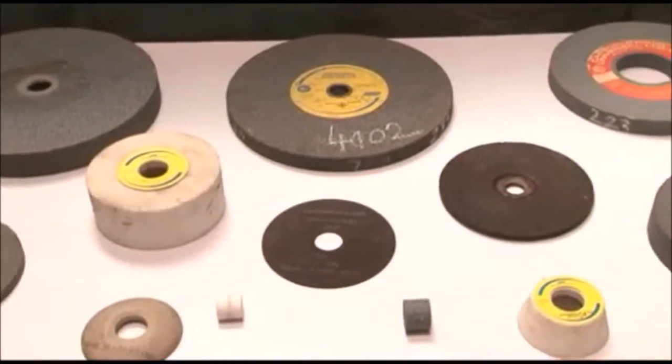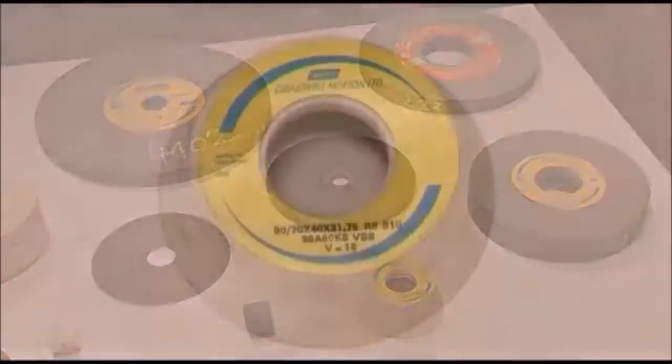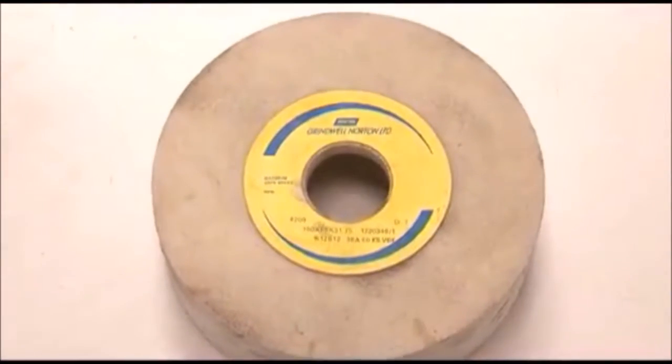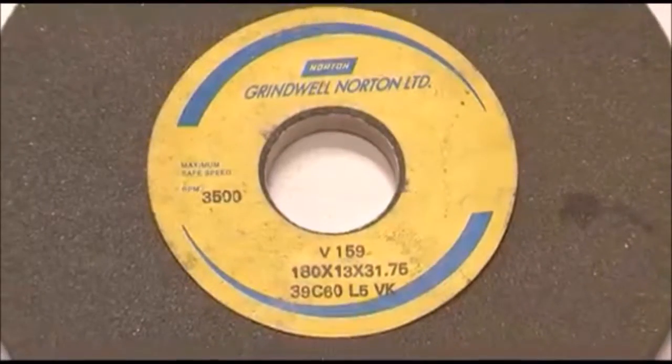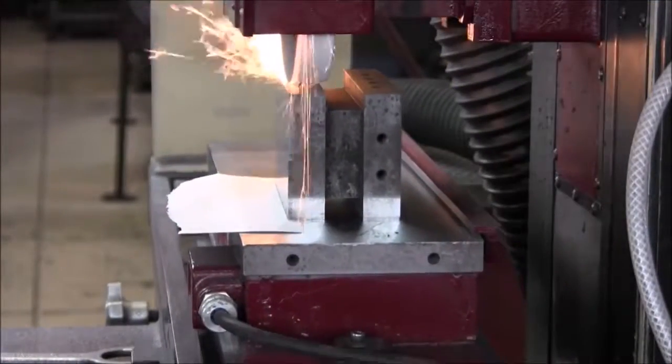Grinding is a machining and manufacturing process used for material removal and surface finishing. The cutting tool in this process is known as the grinding wheel and is capable of removing material with precision unmatched by both milling and turning. This can be used for both tolerancing and surface finishing, both of which are very important finishing tasks in machining.